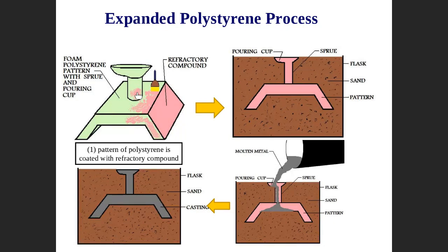Then what you need to do is put the drawing or the design in a computer and allow the machine to cut the foam to create the pattern. So the first step is you create a pattern by using a router machine.